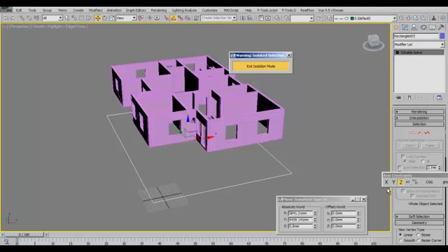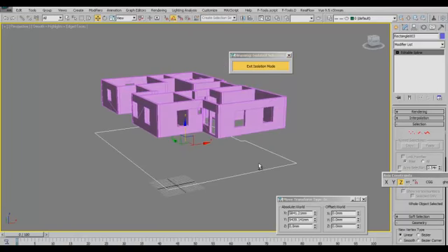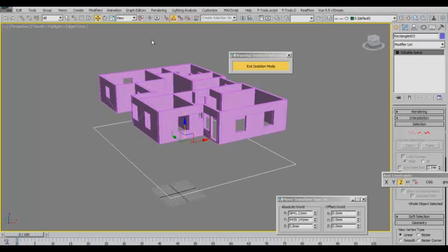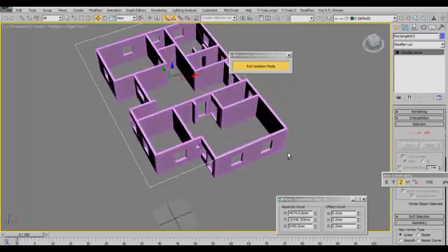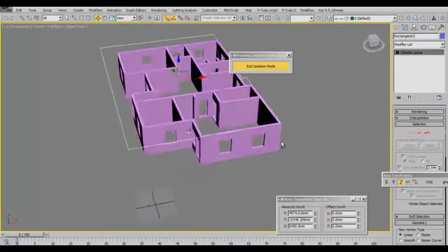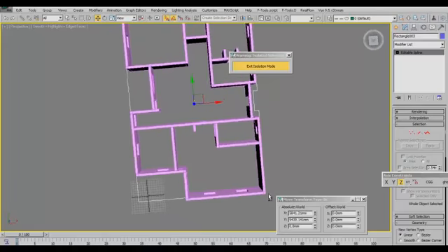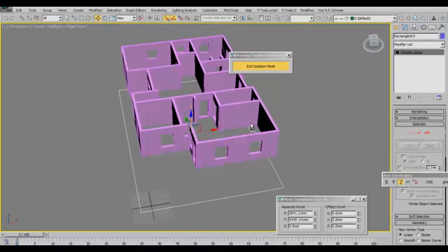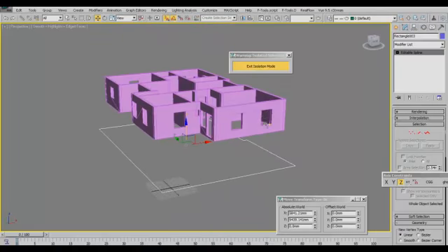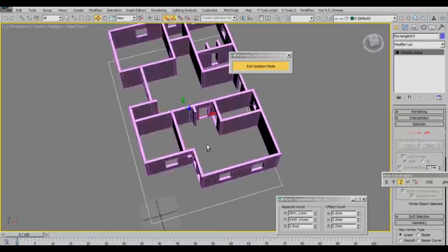So what we now want to do is move this guy up to this point and snap it to this point, and we don't want to snap it with, well, let's turn on 3D snap. We don't want to snap it this way because it's now distorted a little bit. We want to snap it, but still keep it in the positioning it is placed, without moving the position.